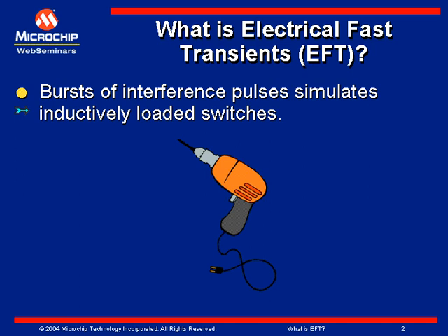But the appliance industry is not the only industry that cares about EFT or electrical fast transients. If you look at an industrial environment, it's even worse than the home environment. You will have huge noise generated by big motors. And that's why you will see that there are lots of industries that require you to perform electrical fast transient testing on your system.